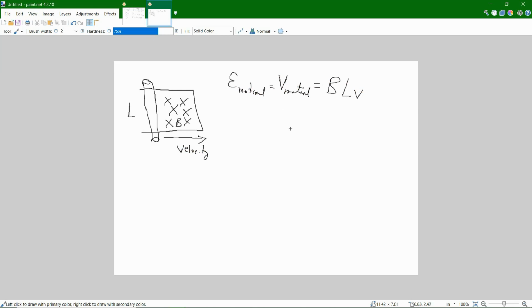So you actually get a voltage across the ends of the rolling pin that is proportional to how fast the metal object is going times the length of the metal object times the strength of the magnetic field. The stronger the magnetic field, the greater the length, the greater the voltage.